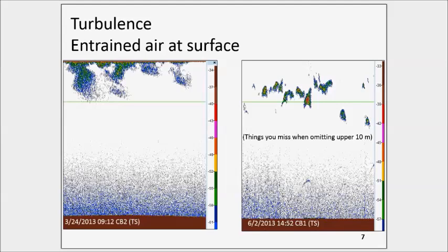Yeah, the work that we've, sorry, this is Garrett Staines in Gail's lab. Our single beam work has been with a wide angle, actually a 31 degree, which has a really, really large main lobe and very, very small side lobes, compared to a 7 degree narrow angle that has pretty significant side lobes.